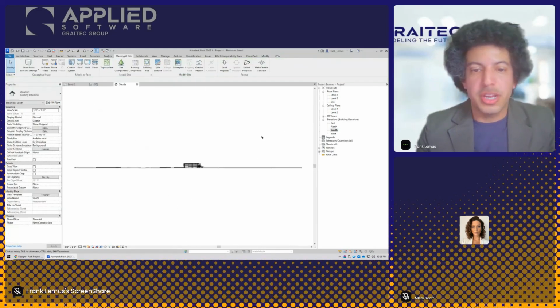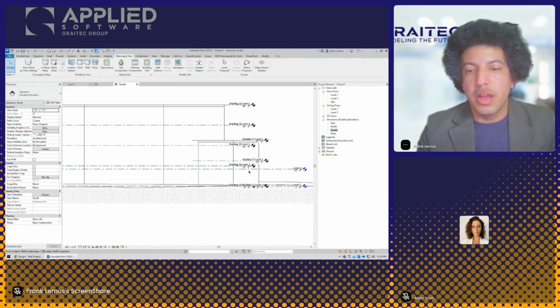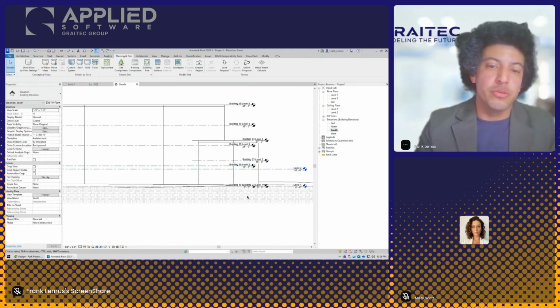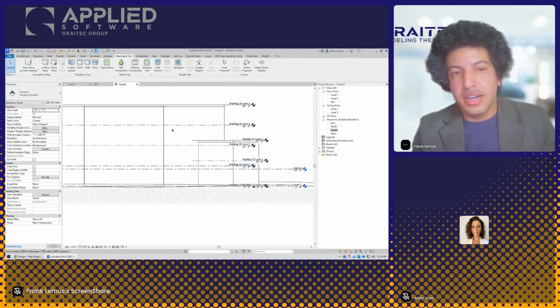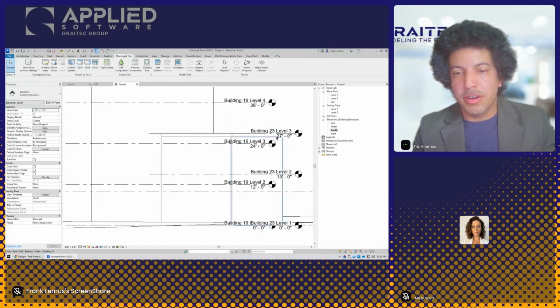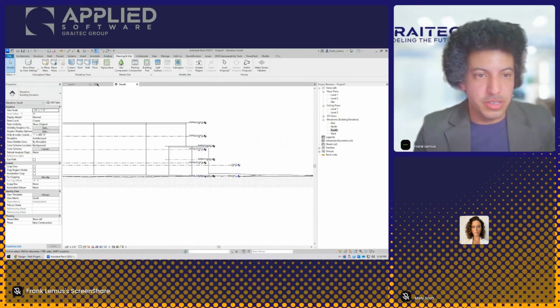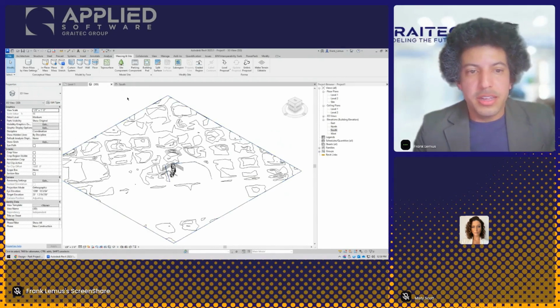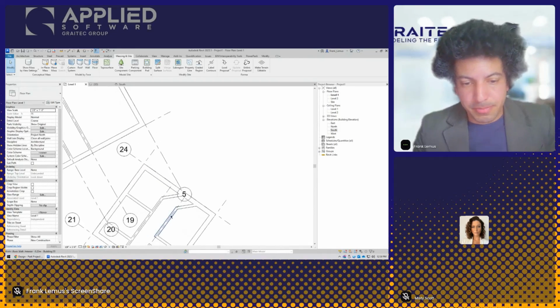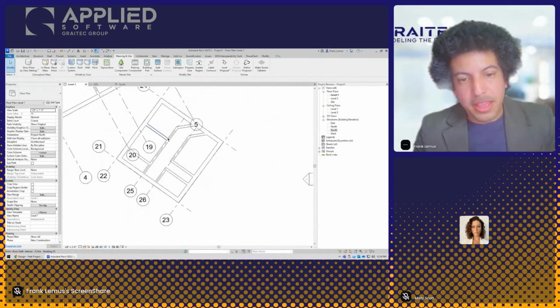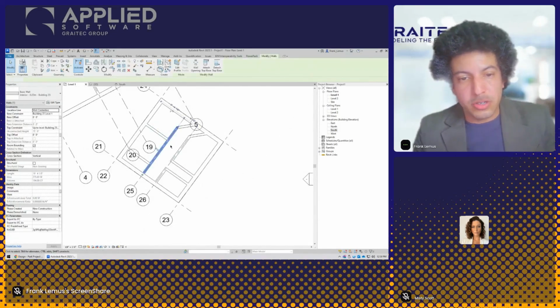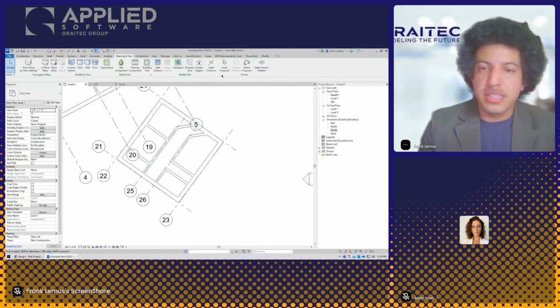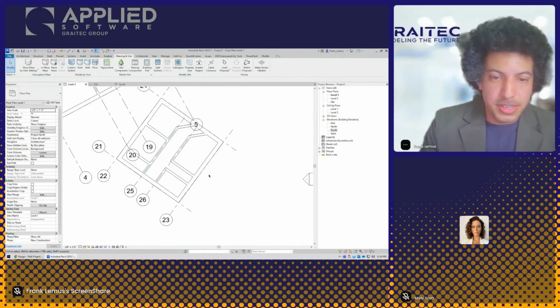It is actually creating levels for you as well, but it's not creating views, so be careful about that. Obviously, the names are very off, so you'll need to determine a way to handle that. The takeaway here is, see how there's our design right there? It's creating actual walls for you if you set that in the settings under load proposal, load options.